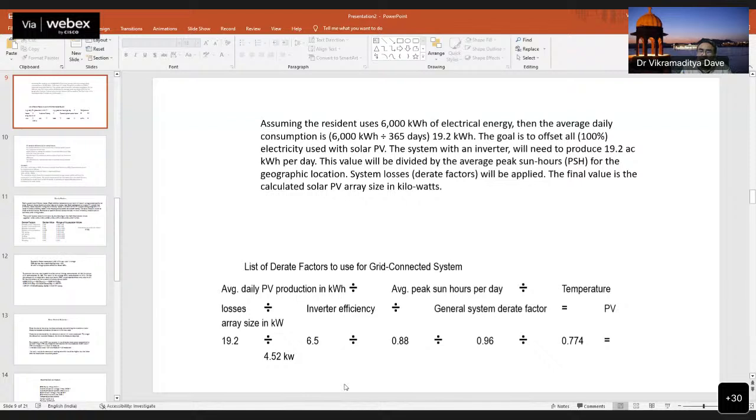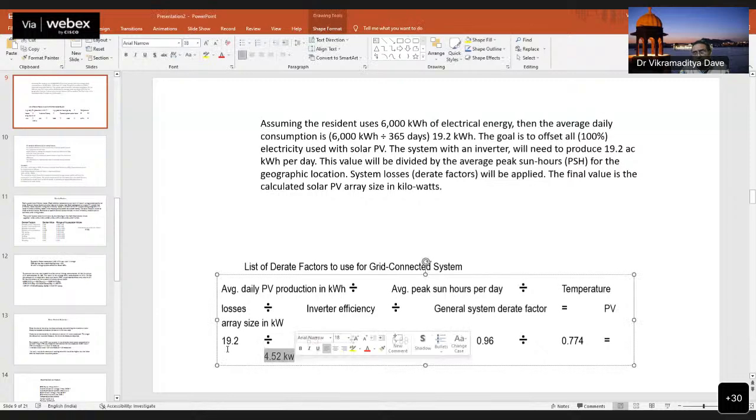So it is better to go for a higher value. 5 kVA is available in the market. Suppose it were 5.5, then you go for 6 kVA. Okay, like this way you have to go for some higher rating than the actual rating of this.